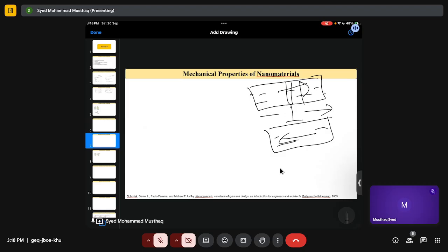That's how it happens. Physically it looks like the upper atomic planes move one step, so that's why you see steps at the end. Whenever a material totally deforms or a dislocation moves from one end to the other, you will get steps. Now, if you have a material and you apply stress, then my slip system is like this, and this part will slip over this part.